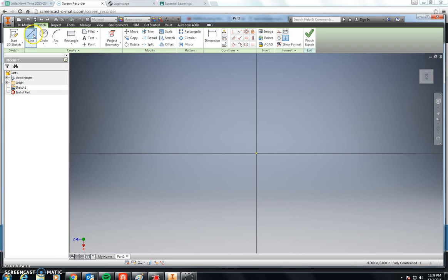I'm going to choose my line tool again and show you another thing. So I'm going to click again to start. I'm going to drag this out. And notice that the box in inches is in blue. So that means if I type any number now, that line will automatically become that number. So right now I'm just going to hit the 2 key. Notice that it actually overrode the number in inches, and if I hit enter, I now made a 2-inch line pointing in the direction I had pointed it. Okay? I'm still attached to the end.